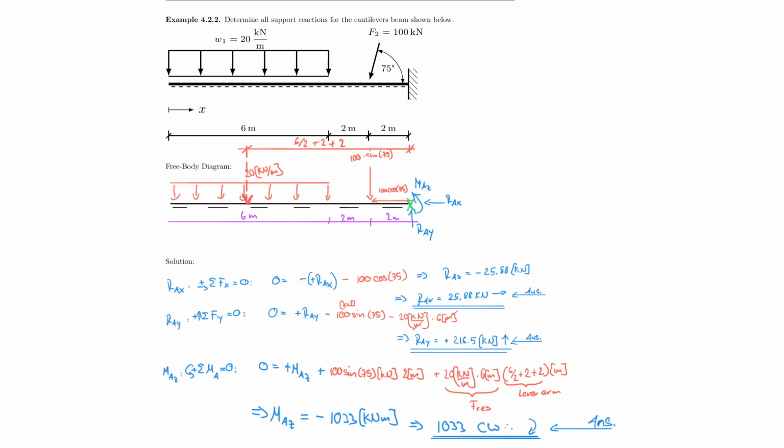And then I showed you that if you have a force under an angle that is resisted here by RAX, which needs to be in balance, that's why we found the negative answer here first. Then we assumed correct RAY, we found that to be positive, and it told us that yes, we have to push up.